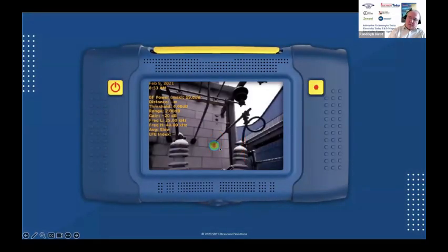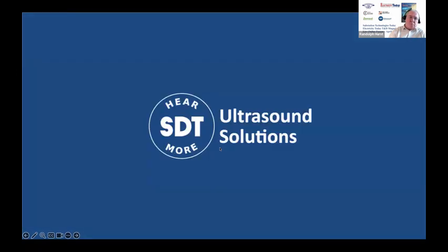Where is ultrasound testing most useful in a substation, and where does it have trouble? Great question. In a substation, I'd say any kind of connection: the phases on a transformer, anywhere where the high voltage cable is connected to an insulator.